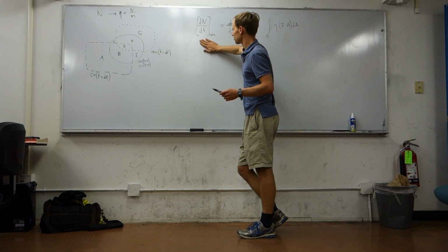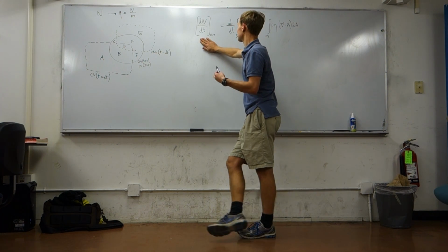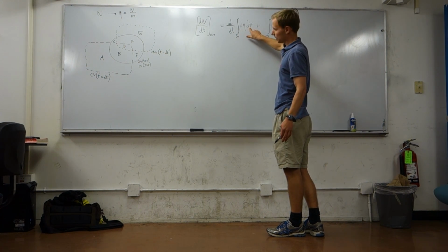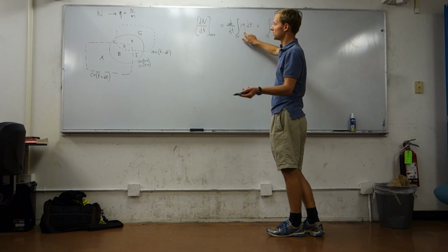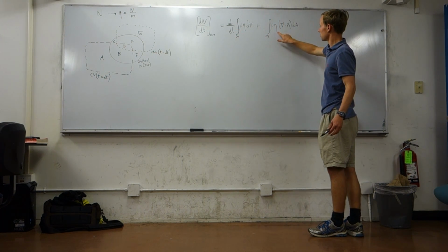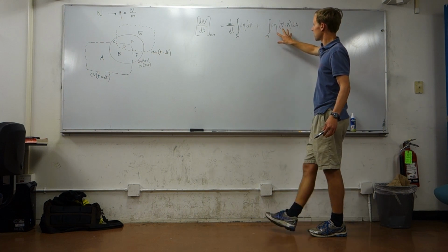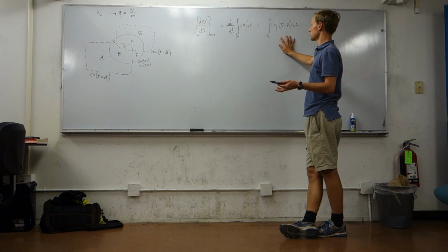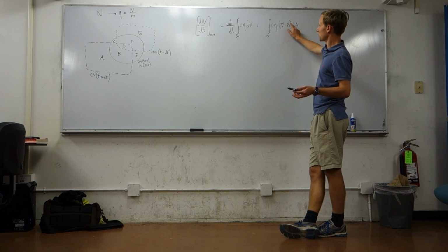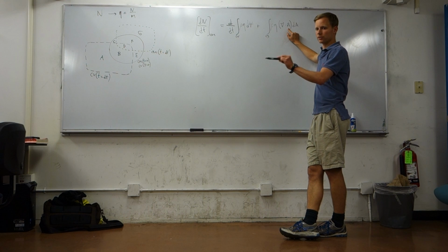So again, we can exploit the laws of physics here, like mass conservation and energy conservation. You can think of rho dV, integrated over the volume, as just a mass. We're multiplying mass times our intensive property, which gives us N, so dN/dt. And then here we're balancing the quantity eta, where eta is multiplied by the mass flow rate out of our system minus inflow to our system. The reason it's out minus in is just because the unit vector n hat is defined positive outward from our control volume.